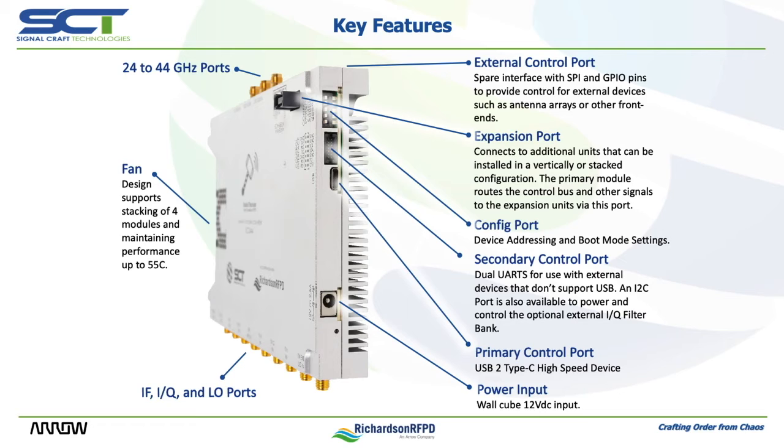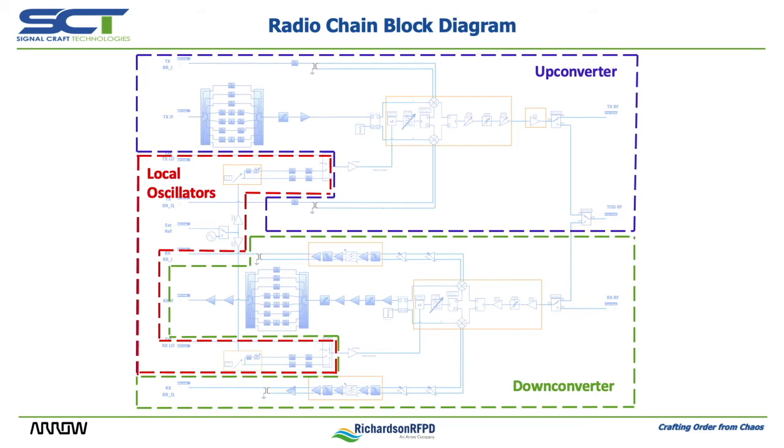The millimeter wave ports, visible on the top of this image, include 2.4 millimeter connectors for the FDD TX and RX functions, in addition to a bidirectional TDD port. This high-level diagram represents the complete radio realized in the converter. We won't dwell on this eye chart, but it's been presented to provide some context for the detailed block diagrams which follow on the next 3 slides.